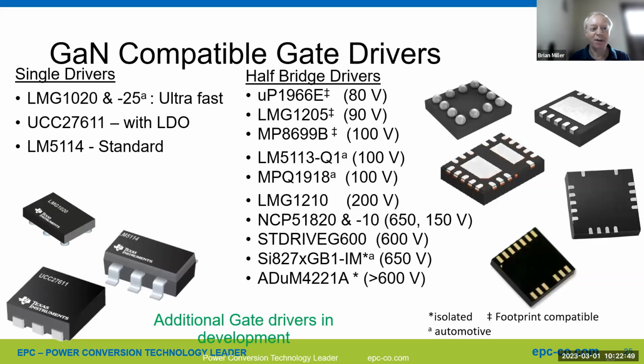On this page, there's a lot of GaN compatible gate drivers. You might ask, well, if it's so simple with 5 volts and 0 volts, why all this here? Well, a few reasons. One's the speed. You want to have a nice fast gate driver. You want to keep under the 6-volt limit on the gate. A lot of these parts have clamps to do such a thing.